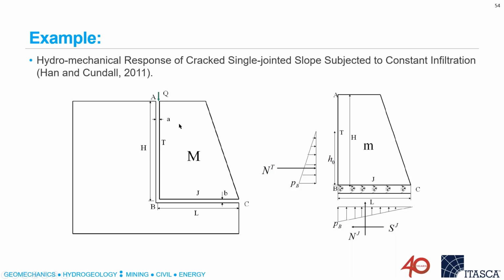What happens is water starts to fill up and build up pressure in this vertical joint behind. As it builds up pressure, it builds up a driving force and reduces the shear strength on the basal sliding surface, and it moves out a little bit until the water can reduce its height, and then it begins to build back up.